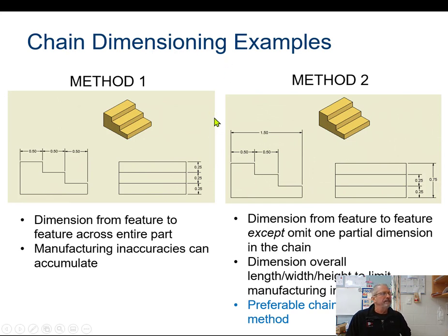Anthony, what is wrong with this? What is wrong with this dimensioning right here? Somebody please tell me. I hope you all said that it was not dimensioned to the shape and it was outside of views. I would absolutely crush somebody on this. These dimensions should be over here. So that should not happen.